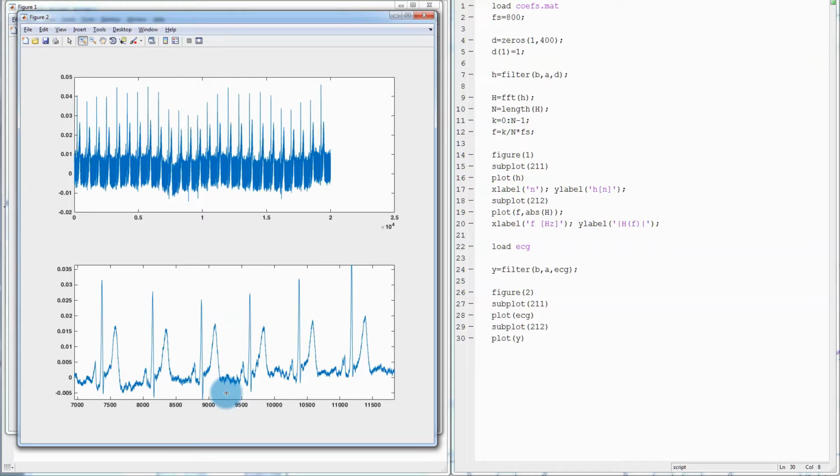Interesting thing to note is that I was able to do this filtering using a filter of second order. So this is a very computationally efficient filter. On the previous exercise we did this by filtering in the spectral domain. For that we had to use much more computational power. So this IIR filter is actually more computationally efficient.